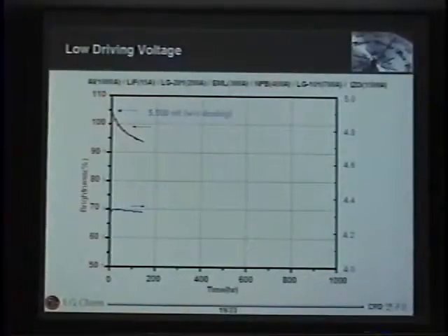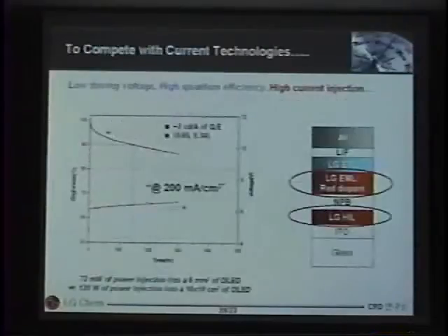And if you use amorphous silicon for the TFTs, since amorphous silicon is N-type, unlike polysilicon which is P-type, you can directly connect the cathode, which is on the same plane as the drain side of your TFTs. So the processing will be even easier. Next.